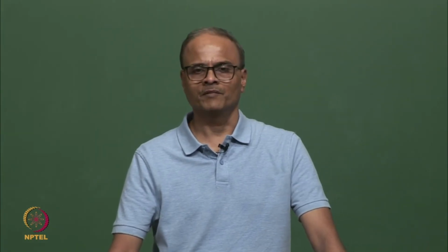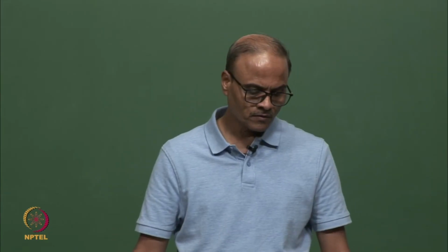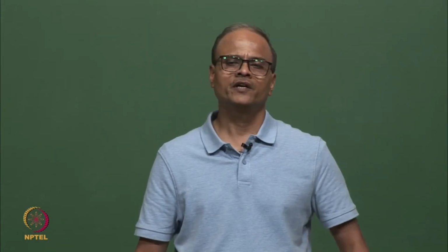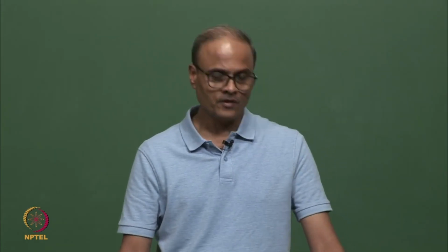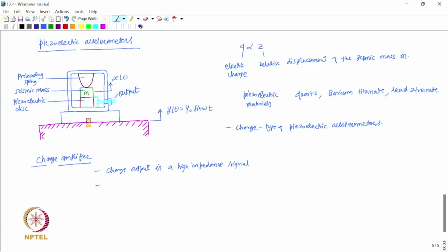That is why we can't directly measure the output of a piezoelectric charge type accelerometer. So this needs to be converted to a low impedance signal, and a charge amplifier is used for that purpose.